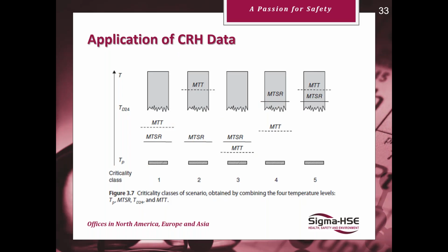Moving on then, we have the class 3, where the technical limit is reached, but the decomposition reaction is not critical. So boiling of the solvent will increase the reactive pressure, and this can be used to temper the reaction as a first sort of measure. Because we're reaching this technical temperature, we will need alternative discharge systems to be designed in this case. This can be, for example, pressure relief valves that can vent off the solvent vapor to temper the reaction mass. But then further downstream, you're going to need to treat that discharge and effluent, especially if it's two-phase flow that's coming out of the reactor.